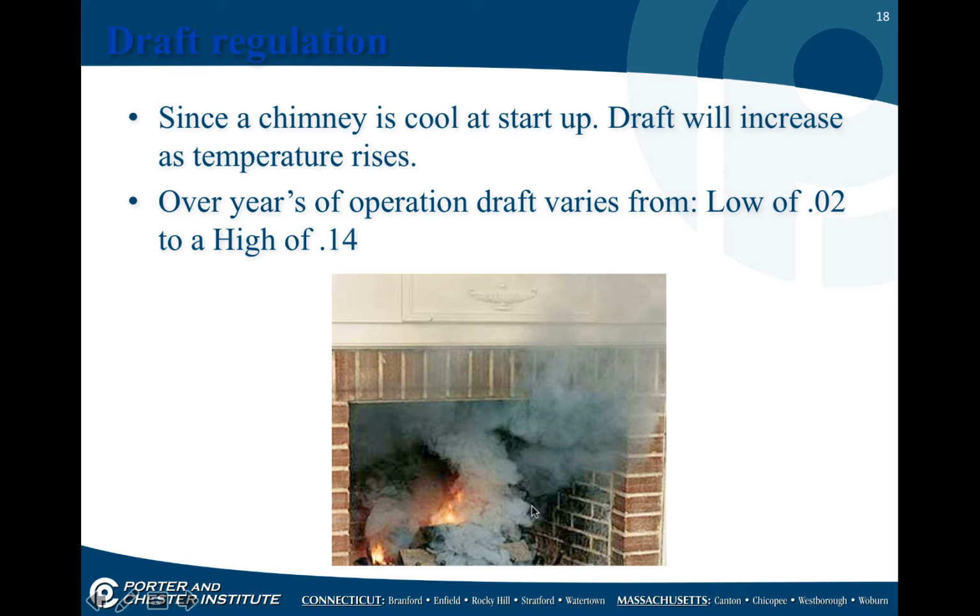Now, if you think about it, or you may have heard of, the experience of a fireplace starting. When a fireplace first starts up, it's relatively smoky. Some people open some windows around when you first start a fireplace to allow cool air in. That's to help create that initial draft. Or you can actually have smoke coming the wrong way out of a fireplace.